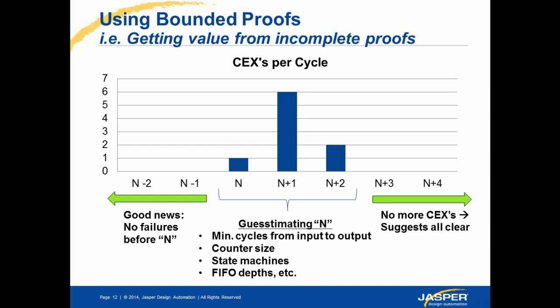And they say, let's say I have run this design till a depth of n or n plus 2. And if I haven't found a counterexample till that, it might run for a day, it might run for 2, but if the tool reaches this depth, it is good enough for me to sign off on my formal verification effort.